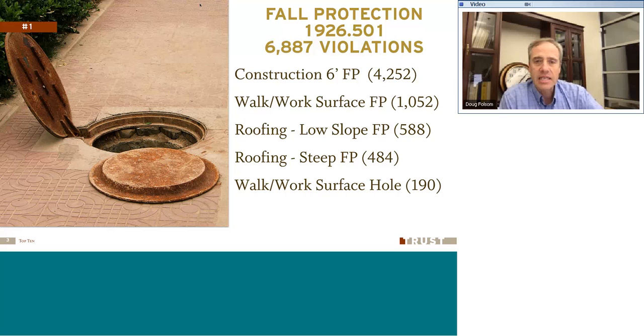And so all of those things are ones you would want to look at when assessing your fall protection program. If you're working at heights greater than 6 feet or 5 feet, depending on the situation, we need to make sure that we have taken into consideration what requirements are there for fall arrest systems or fall protection systems, railings and barriers and so forth.